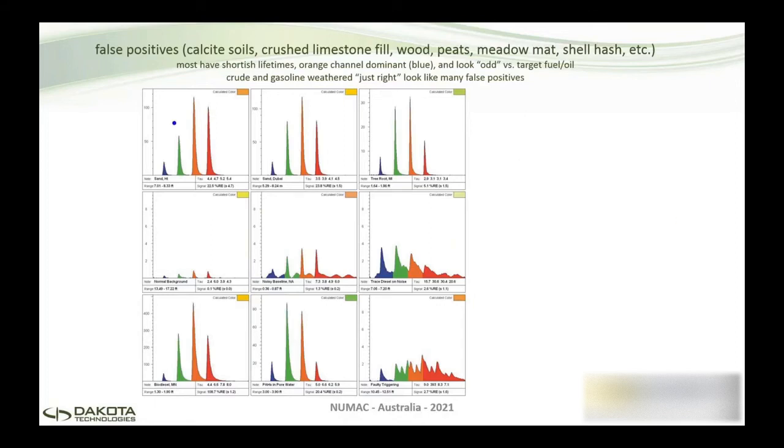And like I think I mentioned earlier, one of the things that false positives almost always do is these last three channels look like Neptune's spear, right? They're relatively short-lived and pretty equally balanced. So this is sand from Hawaii, sand from Dubai. This is a tree root that we went through in the state of Michigan in the US. Okay, so I'll show you how UVOST actually can help differentiate and point those out to you here in a little while.